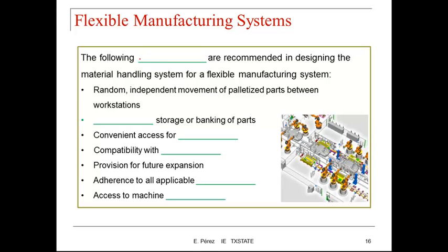The following design requirements are recommended in designing material handling systems for flexible manufacturing systems. First, random independent movement of palletized parts between workstations. Second, temporary storage or banking of parts.